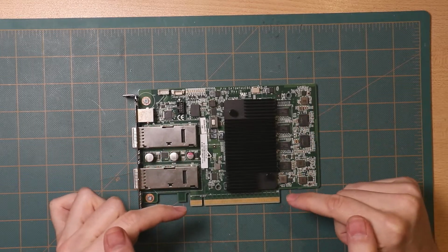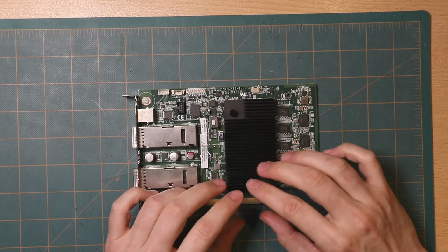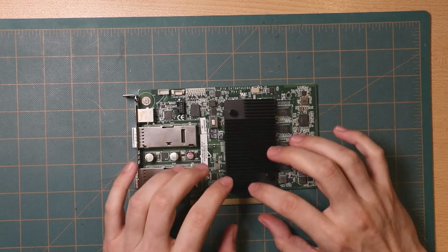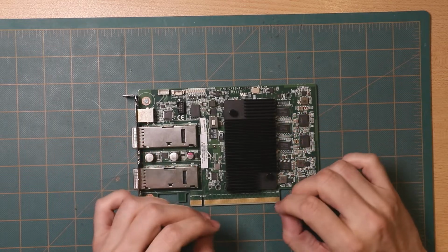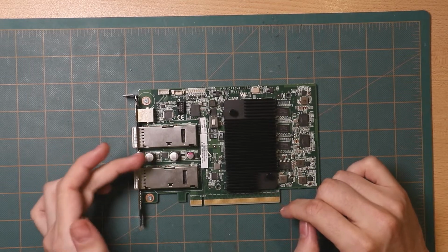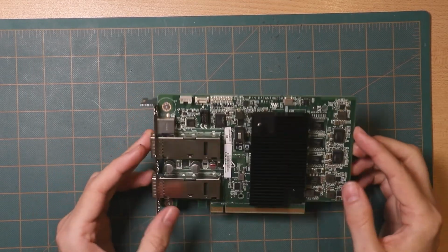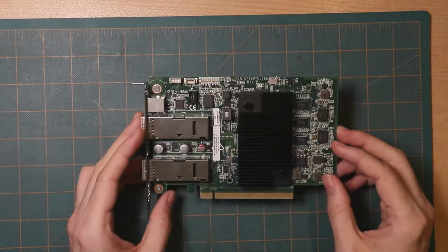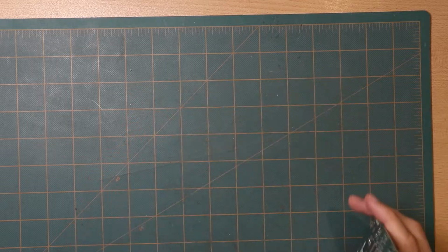That is, bringing up the PCI Express interface, making the model of the hard core in Cocotb PCIe, modifying the PCI Express DMA engine to talk to that, bringing up the Ethernet interfaces, and then making the whole thing work. So that's definitely going to be a multi-part sort of thing. I'll do that at some point. I don't know exactly when, but at some point I want to do that.